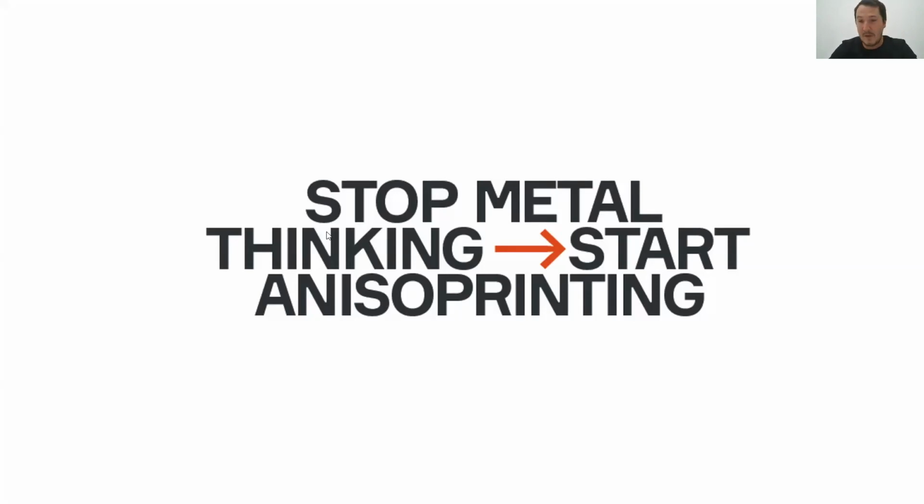So in this case, we are pretty sure that PA12 is a very good choice. It's easy to print with, and it provides good quality, good printability. It's not as strong as PA66, but strength is defined by the continuous fiber.